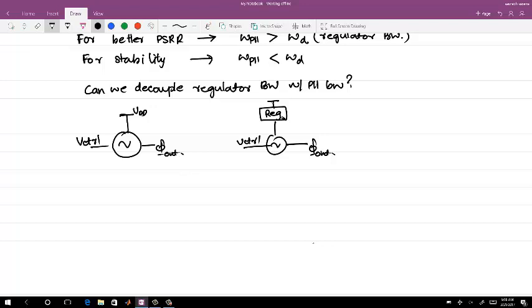If you are not using ring, we can do, but we are using ring. So what you're saying is right. If the control for the oscillator is not coupled to the supply, then you can do it. But if the control to the oscillator is coupled to the supply, which will be the case in conventional ring oscillator control, then it's difficult here. Okay, and this actually gives the way for split tuned regulation in split tune PLLs. So I will go into split tune later, but right now I leave this open because going for the split tune will require understanding more of the loop filter parameters. Okay, we will come back to this, but right now this is the problem.